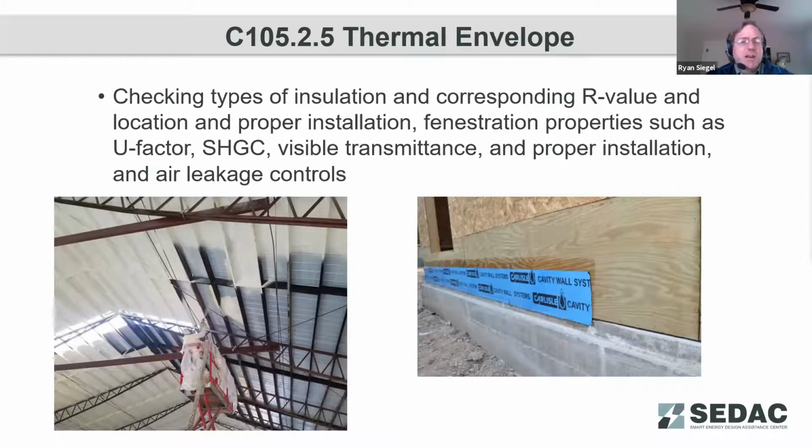On the left-hand side, we're showing a metal frame building, and they're insulating it from the inside using a sprayed-on product rather than a liner system, which may be some more common methods. And on the right-hand side, we're showing where this air seal is going, where the foundation is meeting that wall cavity, and here again making sure that we're following manufacturer's procedure.